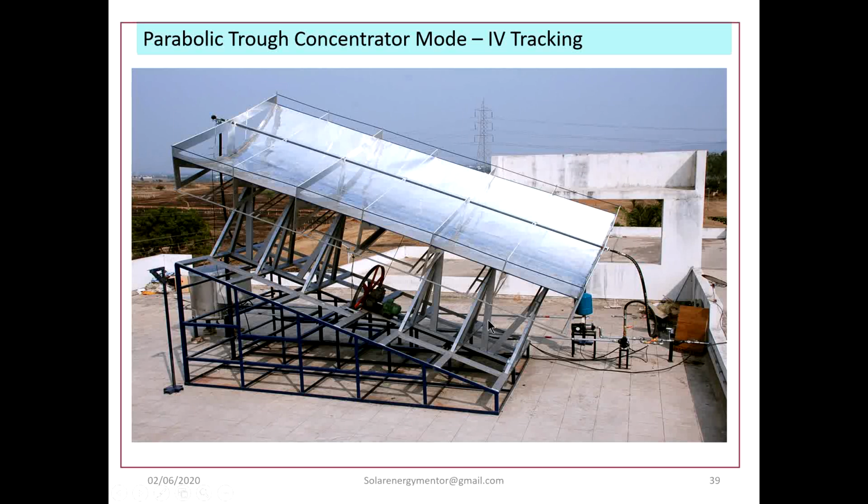Now this 600 kg structure is sitting on an inclined plane. So you can imagine what sort of gravitational loads come in this direction, because this glass tube also starts sliding along this surface, so stops have to be provided at every point. So the entire thing becomes very complicated when we go for mode 4 of tracking, and in addition, the cost of this fixture increases.